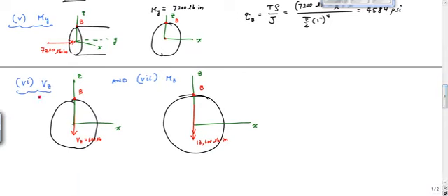And then we looked at the shear force in the z-axis. Because this is at the very top of the section, my shear stress here is 0 due to Vz. So here, shear stress equals 0 due to Vz. And then same thing here, I have a moment acting about z, but I have no distance from the neutral axis of the Mz, the moment about z. So therefore, the normal stress equals 0 due to Mz. Yeah? All right.